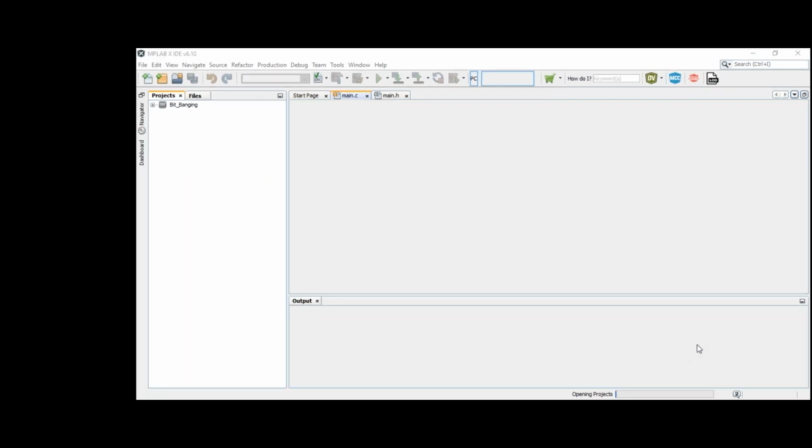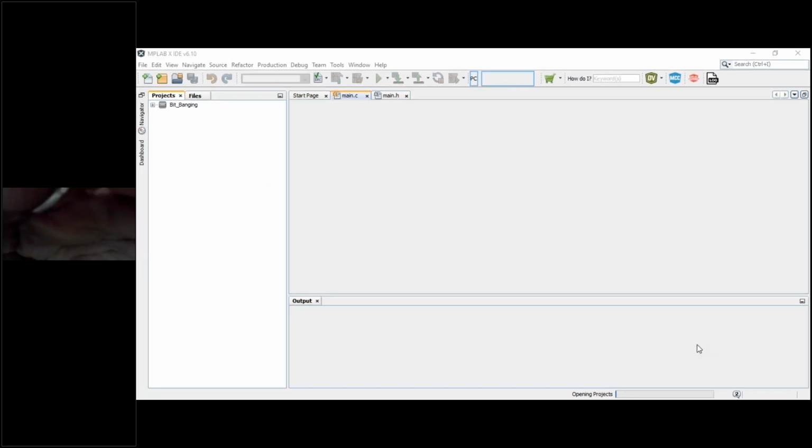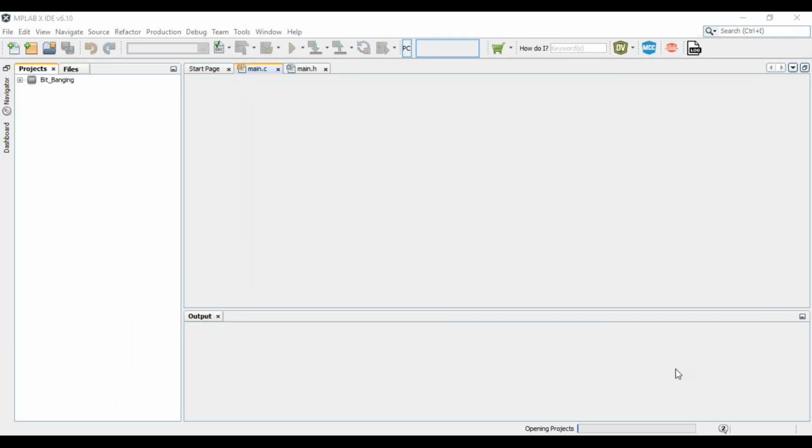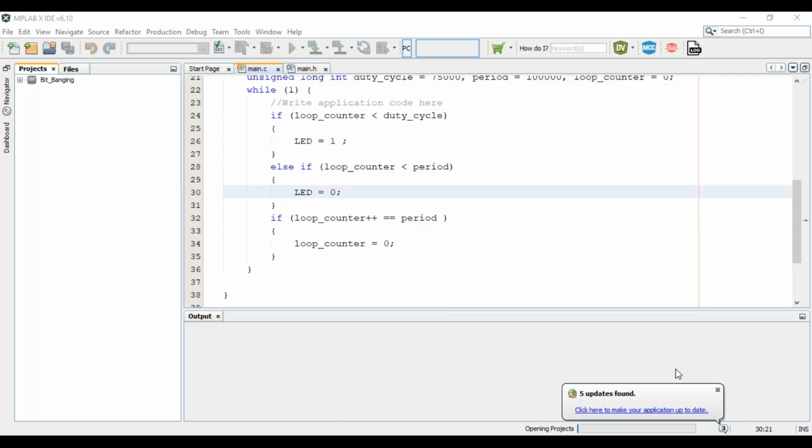Now coming to the PSA. PSA should either be written with the value 0 or the value 1. If I write PSA with the value 0, it is going to assign the prescaler to the timer module. But I don't want the timer to get assigned a prescaler in that way. So that is why I had to write PSA with the value 1.